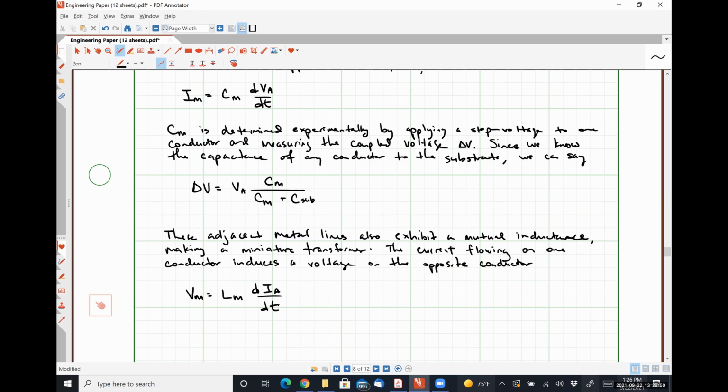But if you have a very, very sensitive system, the minimum rule is just a guideline. If you can afford the space to make your metal runs further apart, make them further apart. Because if you're trying to make a very high precision amplifier and you're constantly coupling and decoupling signals on top that are going to be amplified, how well do you think your device is going to perform? Pretty poorly, right? So it really depends on the application as to how much decoupling and spacing you need between the things.